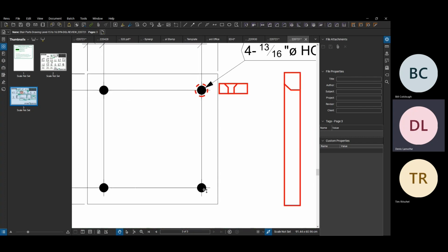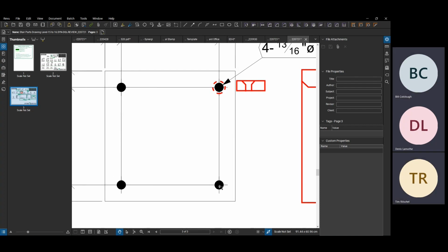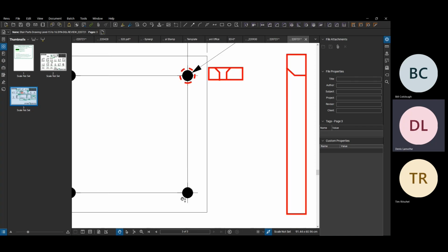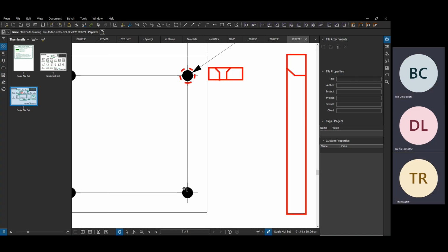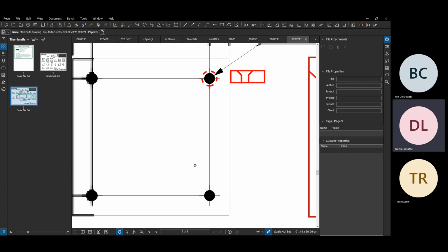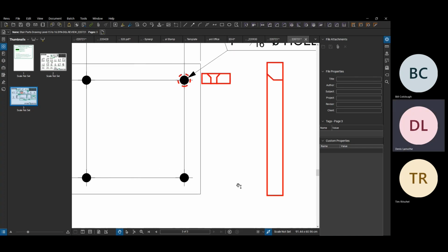Advanced Steel defaults, I think right now by default these holes are hatched solid, so you're seeing the solid black. I'm not a fan of this. I've overridden this myself. Yeah, neither do I. My concern, and I've seen this on another project, was that we had a countersunk or counterbored hole. Oh no, it was an HSS tubing that had a certain size hole on one side of the tube and a different size hole on the opposite.